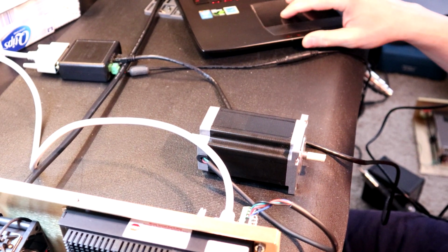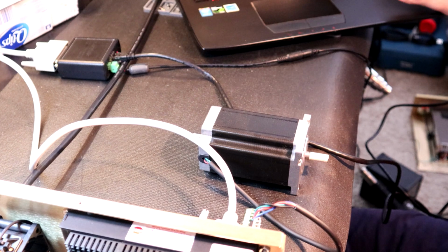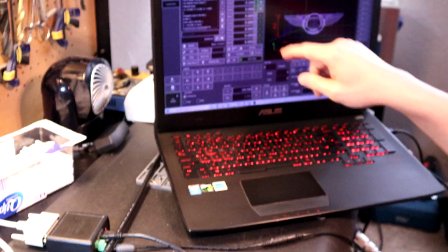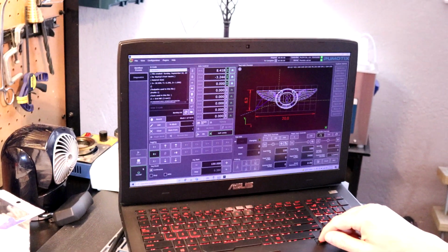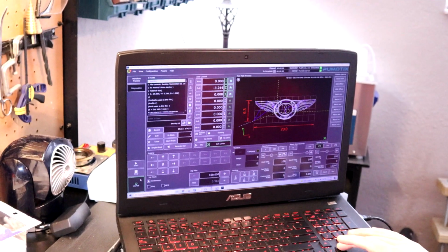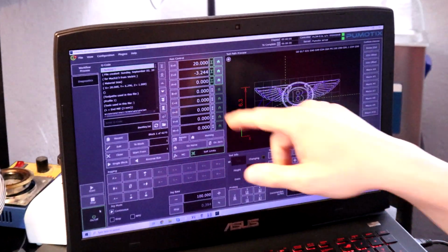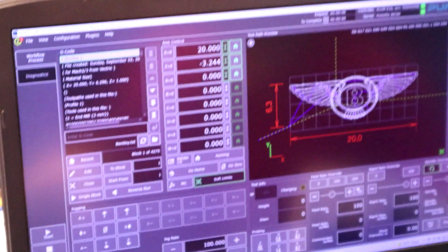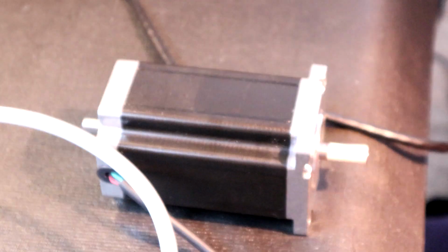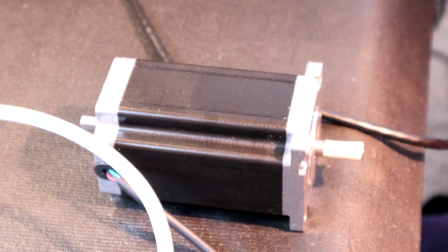We'll turn on our console. Look. Watch carefully. That's it. This software is calculating. There's your soft limit at 20 inches. Look at this. Watch the motor now. Pan on the motor. Let them see it. That's it. That's at 400 steps. There's your 20 inches of travel.